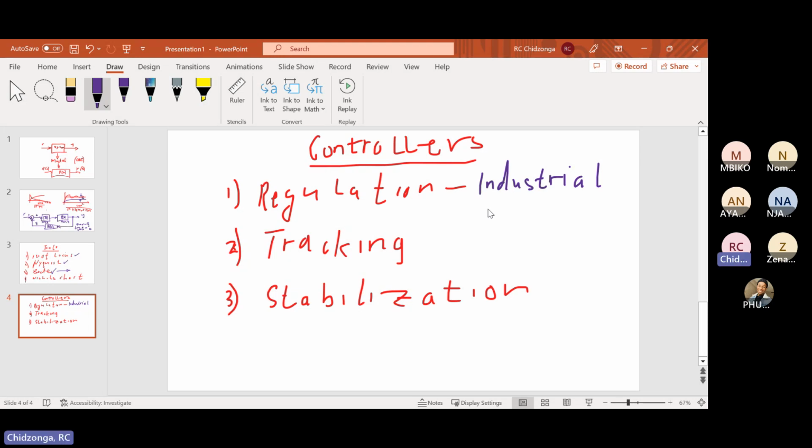You see, that machine can be set and left to produce so many kilometers, maybe to run for 1 week, non-stop. So in that case, what you want is you apply a setting and you want to make sure that the output remains at that setting. In other words, the error should be 0, the input is constant. So you are regulating the output to stay at that constant input reference.